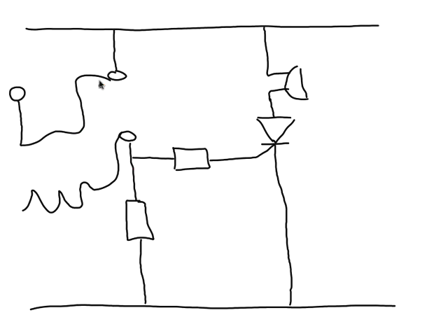But if we simply were to connect these two together, as would happen if the one touches the other part, then we will have current flowing. And we'll have current flowing not only down through the resistor, but also in this direction, which will be enough to give us our pulse. So that pulse will switch on the thyristor. It's already forward biased, so it will conduct, and the buzzer will sound. Now that's great, that's exactly what we want.